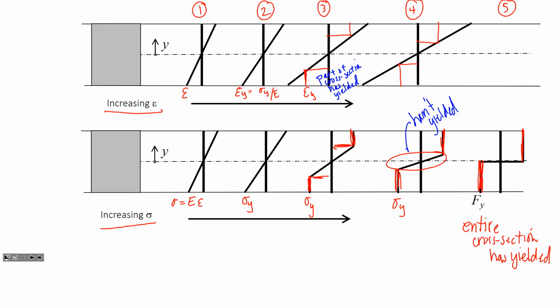Well, what does that strain profile look like? A flat line, right? Infinite strain. It just keeps going. Also known as a plastic hinge, right? Up until you hit yield, you're in the elastic zone. Once you hit yield, you're in the plastic zone. And eventually, enough of your cross-section has yielded that you've created a hinge. It's technically still connected, right? But you're just going to be bending around that hinge. It's a hinge now. It's not holding anything up. So you lose stability.